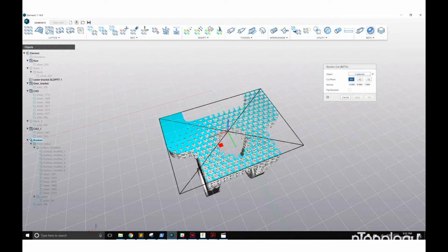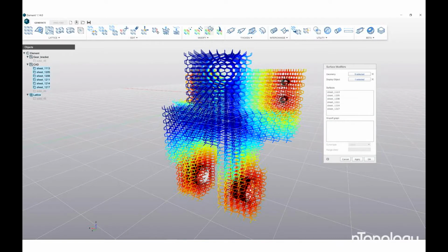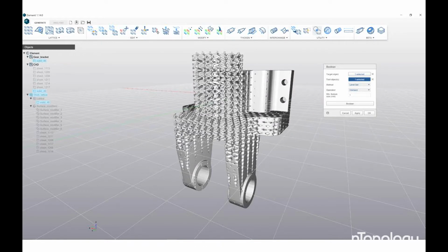In this case, we're using that volumetric representation to extract a clean gradient surface from the part while maintaining those mechanical features. And you could also apply the distance field based on the graph, right? With the graph, we can represent even more complex structures because it's a little bit lighter weight. And then we can combine, go from graph to volumetric, volumetric to mesh, CAD to volumetric, et cetera. So you can still have a boundary representation where you want clean mechanical features, but then you can have the graph for the lattice.